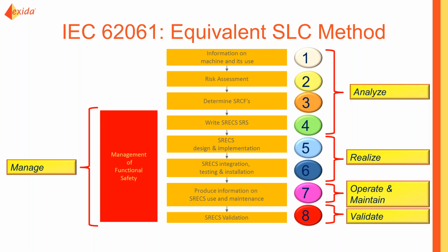I will say both IEC 62061 and ISO 13849 I feel are weaker on the safety lifecycle requirements than, say, IEC 61508 would direct. So we think it's important to look at the requirements within these machine-specific standards, but also then broaden the view to say, is this a robust life cycle, or what other things should we borrow from 61508 or a parallel standard such as IEC 61511, which is a better, more well-defined life cycle for operations and maintenance and the whole everything you need to consider.